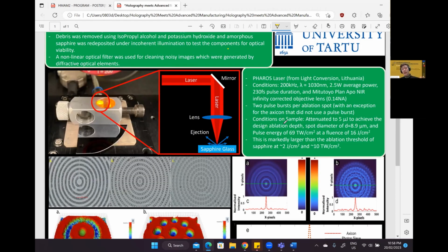So what is femtosecond laser fabrication? Well, it's a process by which a laser uses pulse durations of 200 femtoseconds to rapidly bombard a surface. This causes high intensities to build up on the surface of the material and cause essentially an explosion, which ejects some material. This rather violent yet controllable method allows us to fabricate any number of 2D or 3D devices at our will. Essentially, the limit here is your imagination.